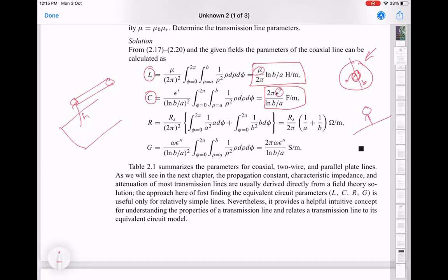In fact, I should really open both the things and lay them out flat. So it really looks like a parallel plate capacitor, right? So for a parallel plate capacitor, you know that the capacitance basically depends on the distance between the plates. So here in this geometry, if you want a smaller distance between the plates, then that means B over A has to be close to 1. And if you want a larger distance, then B over A has to be larger than 1.